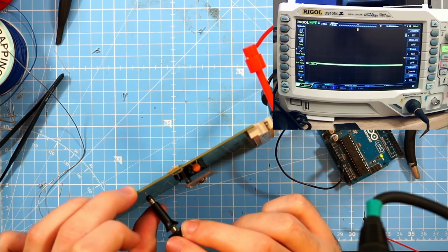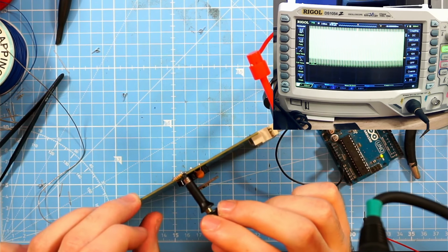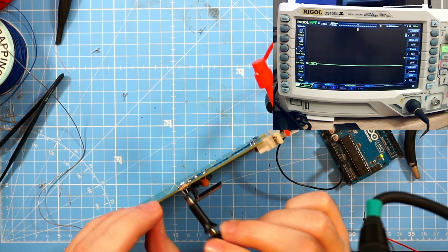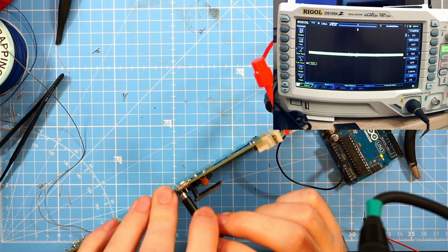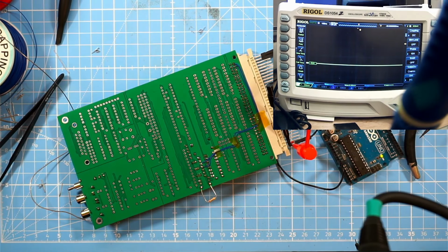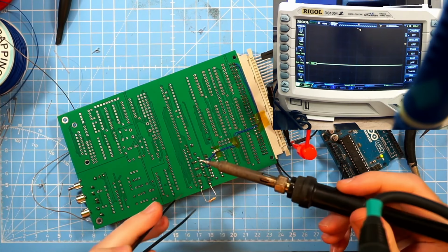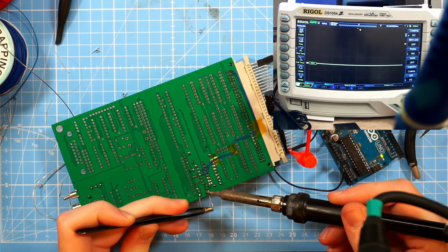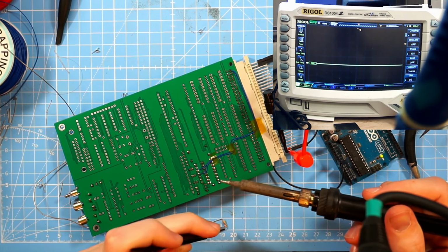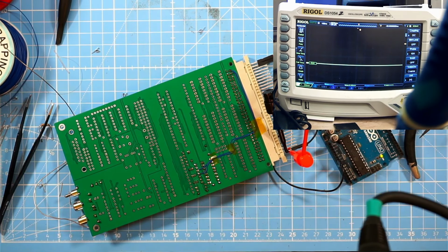But at least right here, just the input, that's the output. There is at least something. I have to find another solution. I don't want to make a new PCB. That was the thing that I was least worried about. I thought that this would work, because you see it does work with frequencies below 10 kilohertz. It does work with 10 kilohertz, but it doesn't work with 7.67 megahertz. Which is disappointing, and now I have to think about another solution. I'll be back once I have another idea.